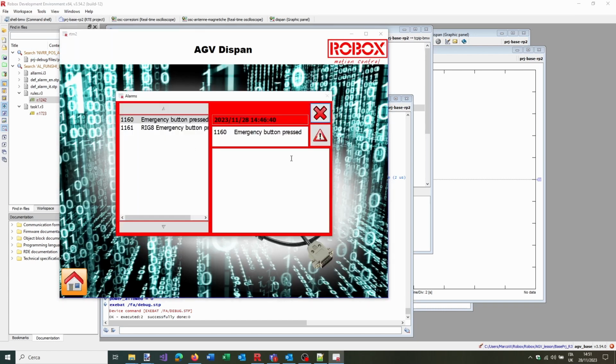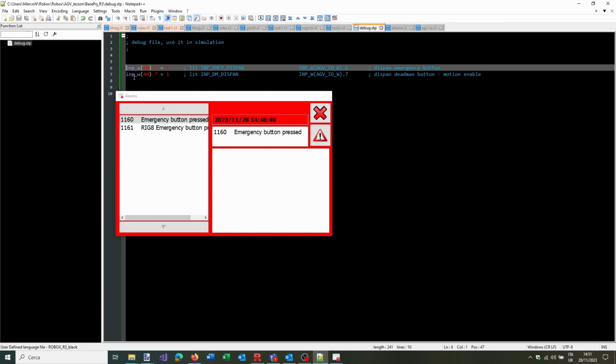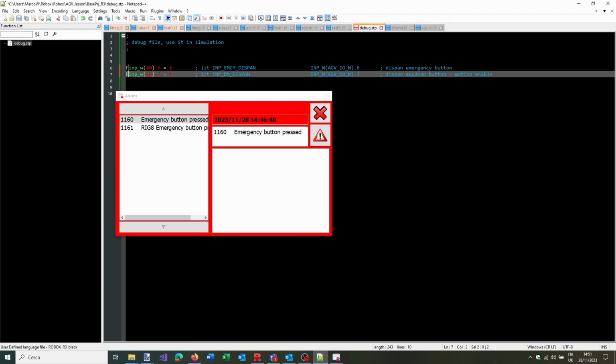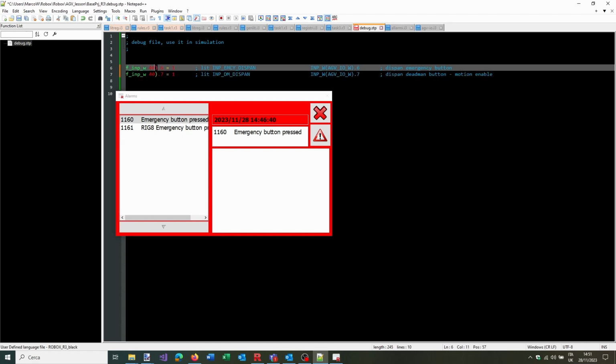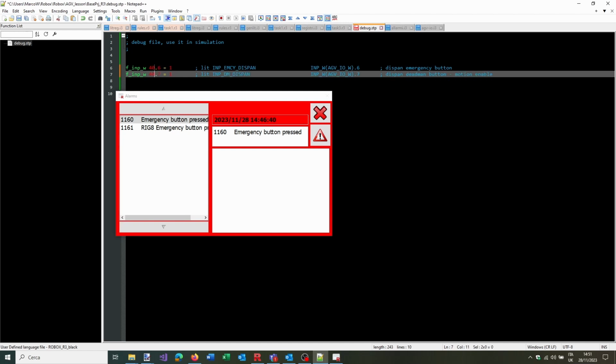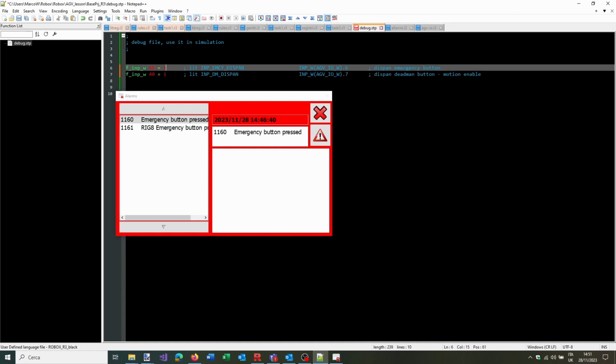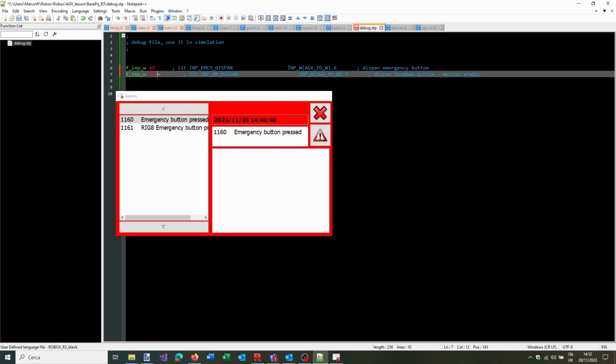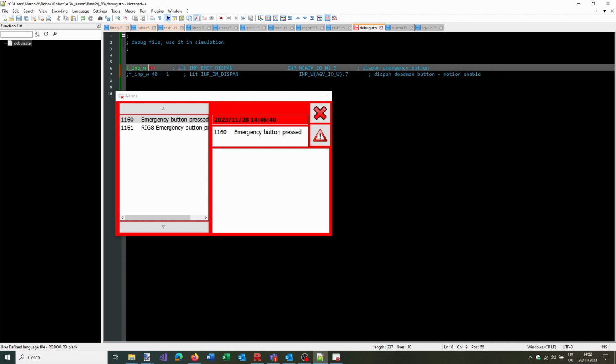So maybe we need to do something else. Yeah, I need to force. All right. So I need to force input word. And so, okay, in case we need to force this input word, maybe I just need to force it to, let's say this is something useless, and this is 0x. I need to use bit 6 and bit 7, so this should be a C0.